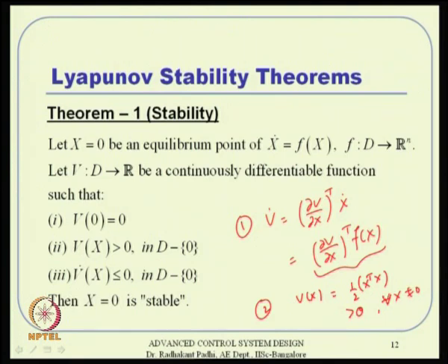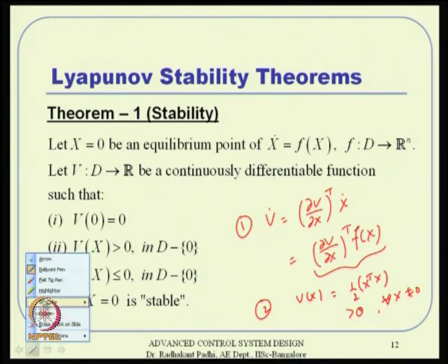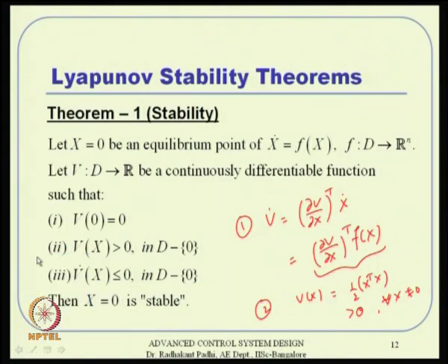So, if nothing is given to us, then this is certainly what we call a Lyapunov function candidate. That means any selection that is positive definite is certainly a Lyapunov function candidate, but once the third condition is also satisfied, then we call that a Lyapunov function. That means it has some meaning to the system dynamics that we have actually.